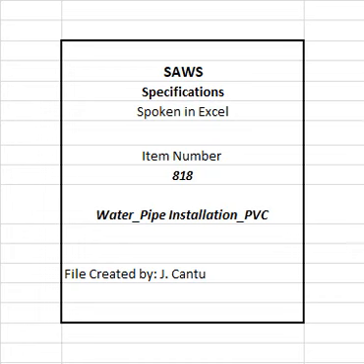5. American Water Works Association, AWWA. A. AWWA C900, Polyvinyl Chloride, PVC, Pressure Pipe and Fabricated Fittings 4 in through 60 in, 100 mm through 1500 mm. B. AWWA C909, Standard for Molecularly Oriented Polyvinyl Chloride, PVCO, Pressure Pipe, 4 inches through 12 inches, 100 mm through 300 mm, for water distribution.